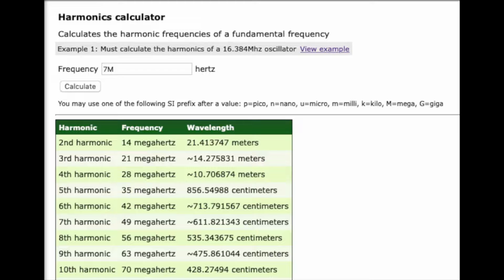And generally, seeing up to the 9th or the 10th harmonic would be fantastic, right? So if we say we want to be able to see the 10th harmonic and we have a 70 megahertz bandwidth limit here, we can see down to like 7 megahertz or something like that. But that changes, of course, if you say we're fine with going through the 5th or the 7th harmonic for square waves. Or again, if you're just looking at sine waves or sinusoids of some kind.